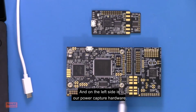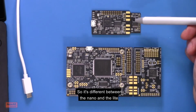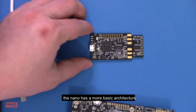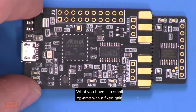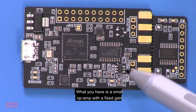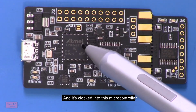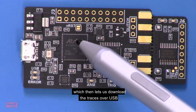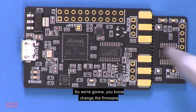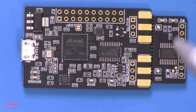On the left side is our power capture hardware, and it's different between the Nano and the Lite. Quickly, I'll talk about the Nano first. The Nano has a more basic architecture. What you have is a small op-amp with a fixed gain, an 8-bit ADC, and it's clocked into this microcontroller, which then lets us download the traces over USB. We can also program the target through this, so we're going to change the firmware. We're going to build our own firmware that we program onto it.